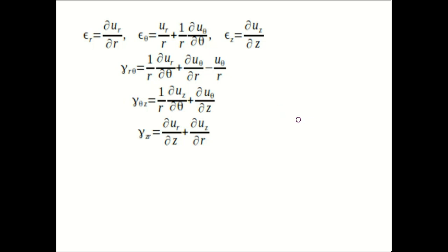Now here, we know that for an axisymmetric problem, everything, stresses, strains and displacements, are independent of theta. So every term which shows ∂/∂θ will go to 0. And as every displacement is independent of theta, these terms will be 0.